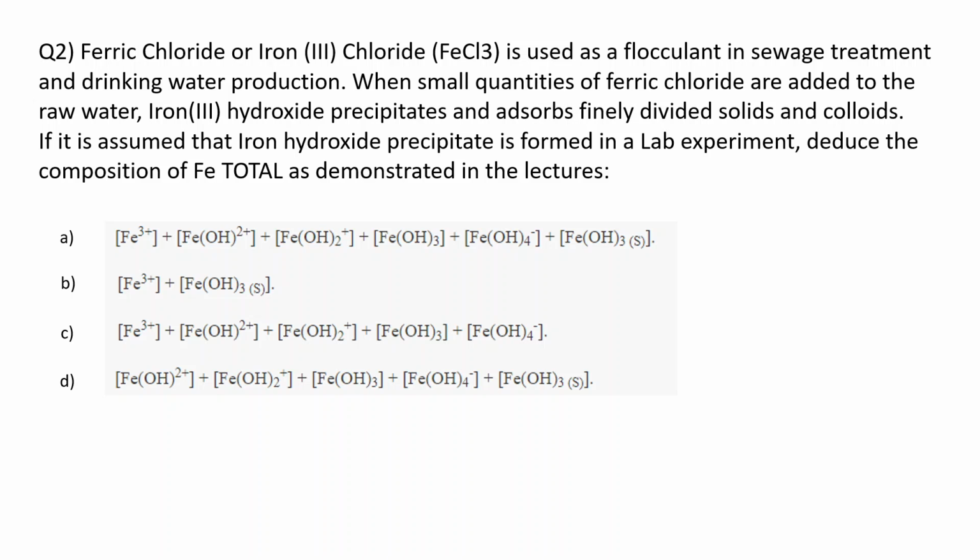So we use some ferric chloride. What it will do is start forming flocs, and in that process, by different mechanisms, it will start taking different colloidal particles with it, and they will settle down. So this is the process of flocculation. I hope that you are already aware of this process.